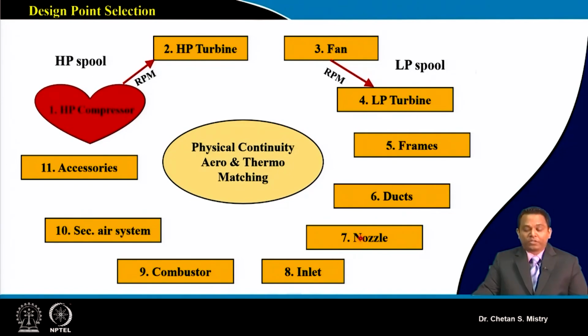Then we look at the nozzle. For subsonic flights or commercial aircraft, we do not have many constraints, but for fighter aircraft it is a major governing part. It has to perform a number of actions, not only thrust generation, but sometimes handling thrust vectoring too. So all those things come into the picture. What kind of engine we are designing decides what focus needs to be applied.